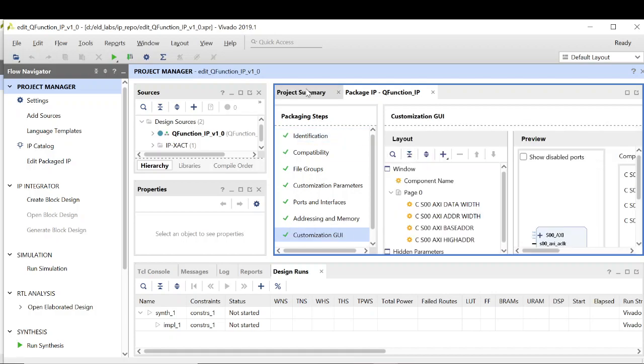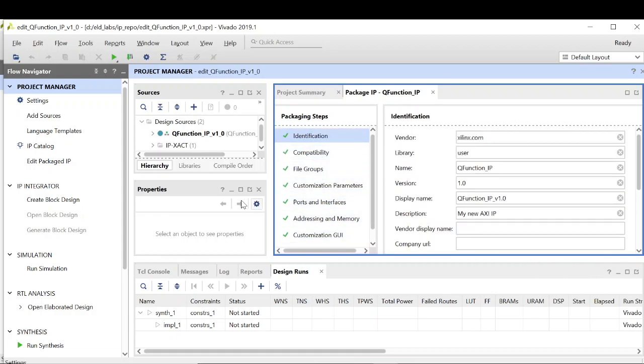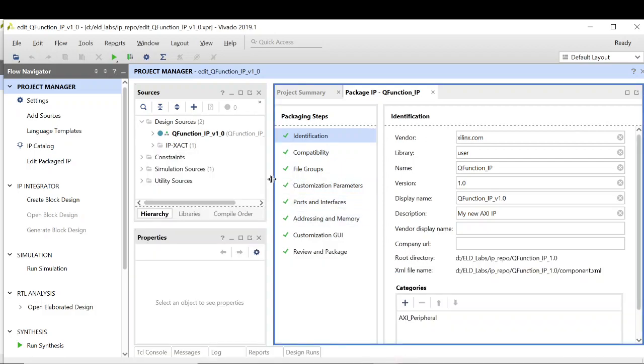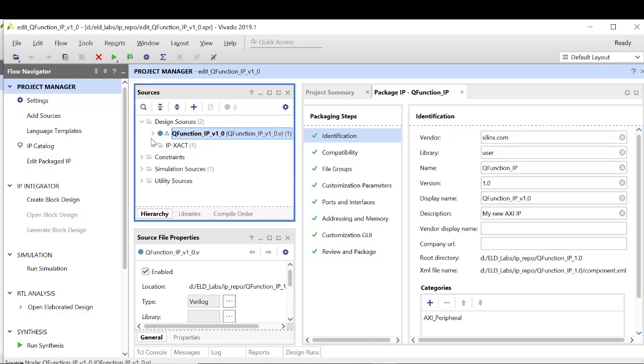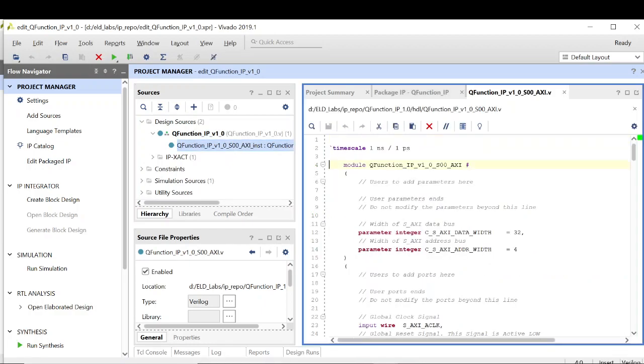All right. Once we get in here, we get the project summary, and we have all these things. Two default Verilog files you can see whenever you create a project. One is your top file, and in it there is this slave file. This is a template code which is already written. In this code, they are just writing and reading those registers that we just specified. We specified 4 registers, so in this complete code, reading and writing transactions are happening.